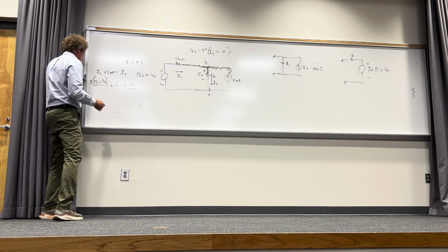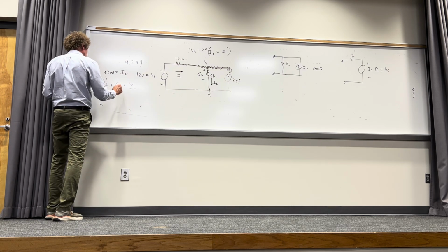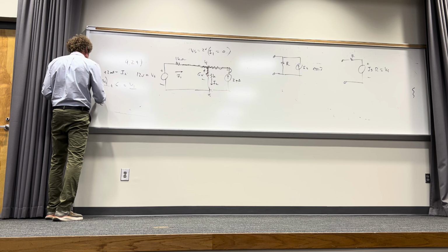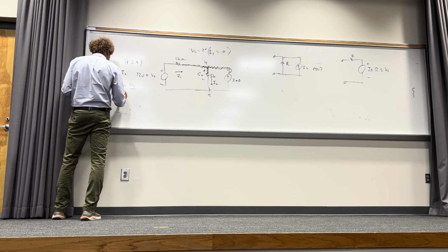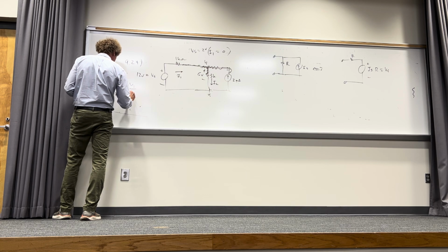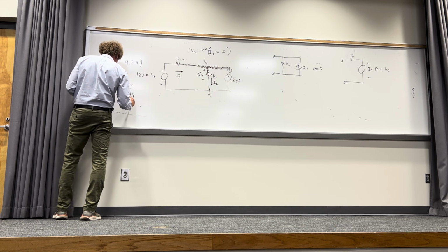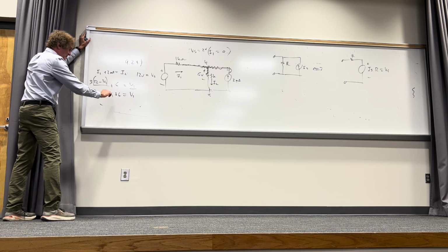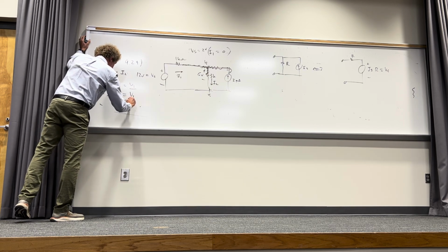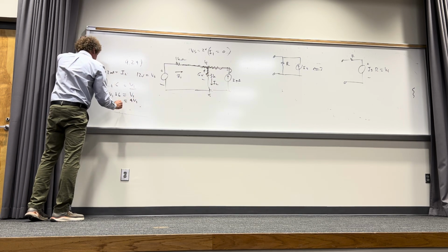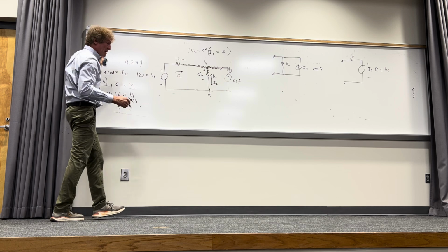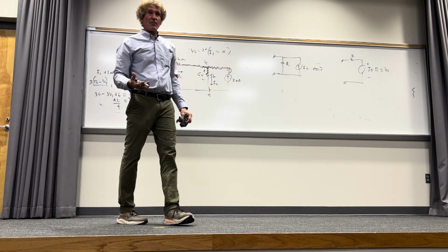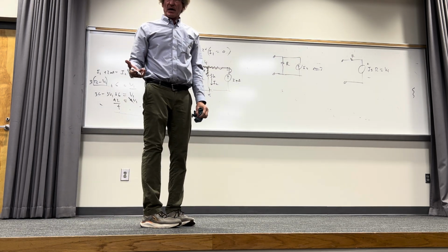And then, when I go ahead and do this, I'm going to get 36 minus 3V1 plus 6 is equal to V1 right here. And then I take the minus 3V1 to the other side, I get 4V1 is equal to 36 and 6, which is 42, or 42 over 4 is V1. Are we in agreement so far? And you can get the currents that way. How many see this?